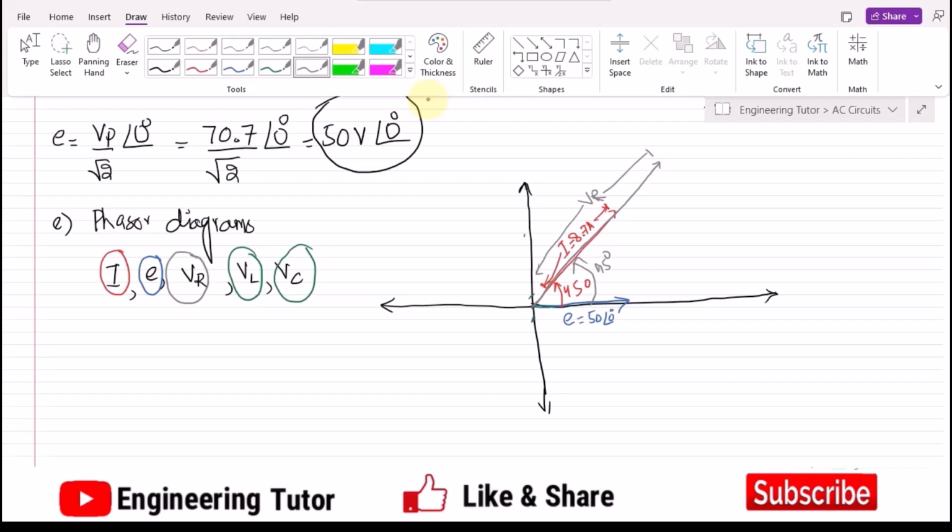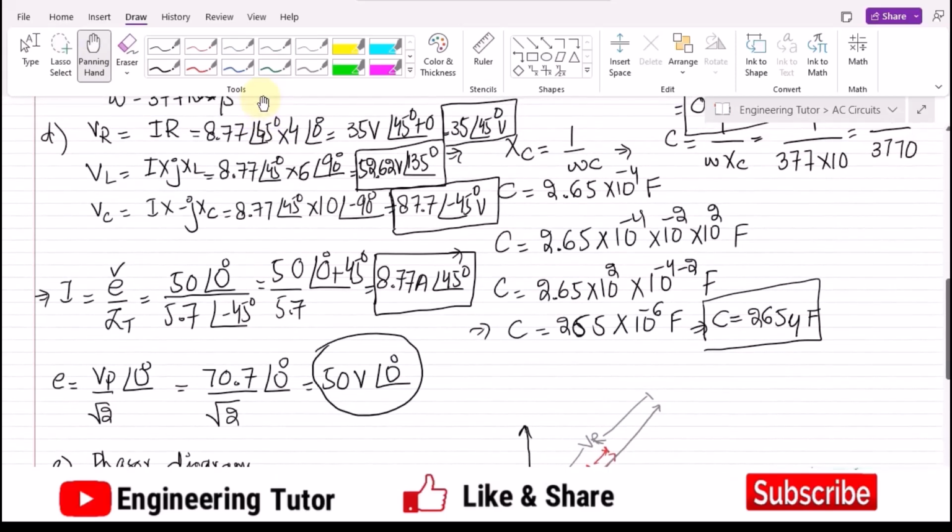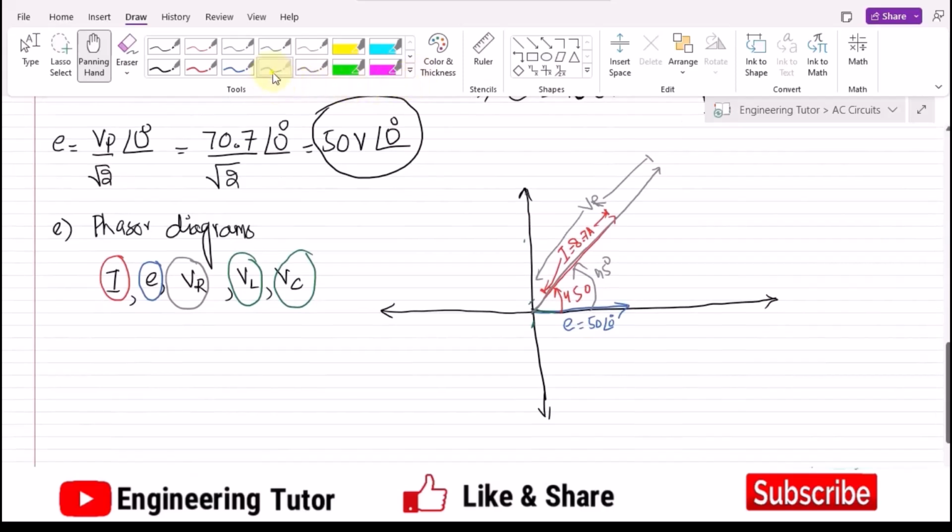After it, let me draw the values of V of L and V of C and represent them with this green color. So the value of V of L here is how much? That is 52.62 with the angle of 135 degrees. So this is 90 and 135 almost lies here.